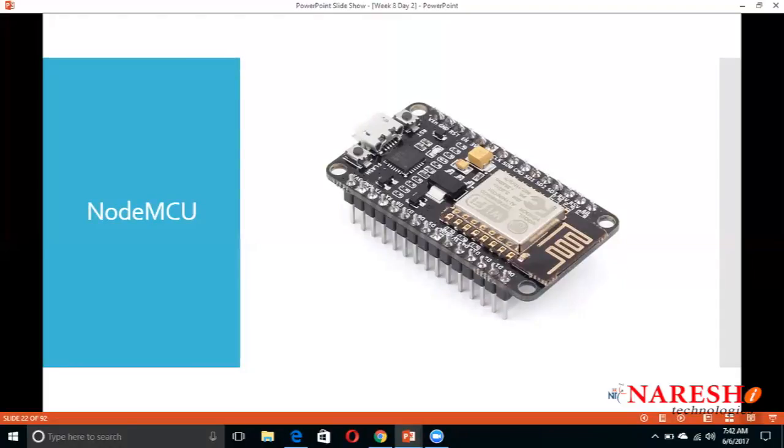That one is the ESP8266-01 module, and this one is the ESP8266-12E module. The 12E is an advanced version with some more specifications of the previous ESP8266 version. And the 12E version module is known as NodeMCU. It has more GPIO pins and other specifications compared to the previous version.